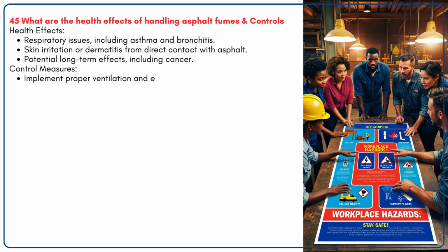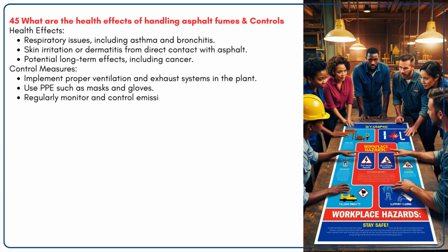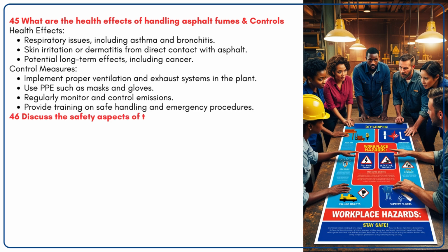Control measures. Implement proper ventilation and exhaust systems in the plant. Use PPE such as masks and gloves. Regularly monitor and control emissions. Provide training on safe handling and emergency procedures.